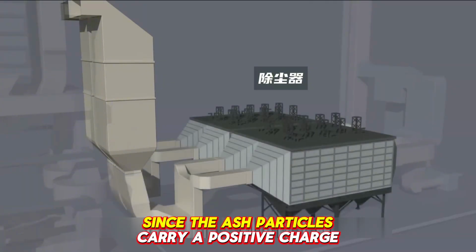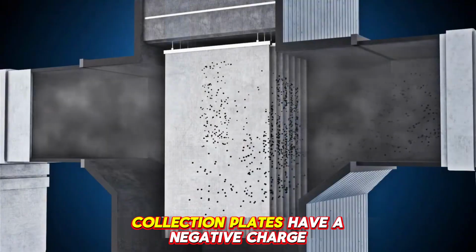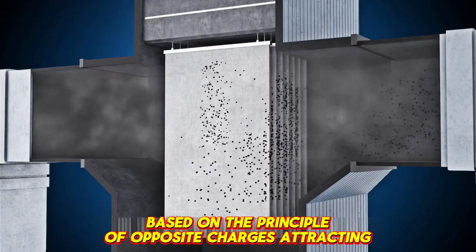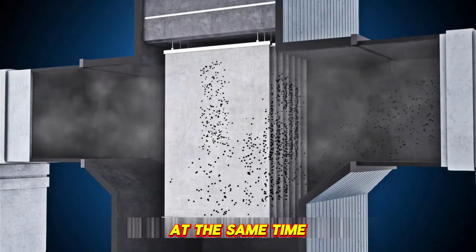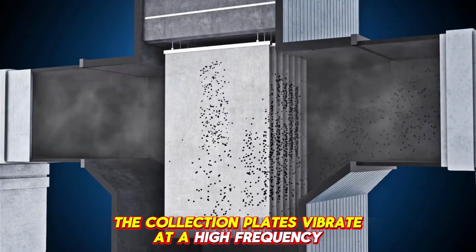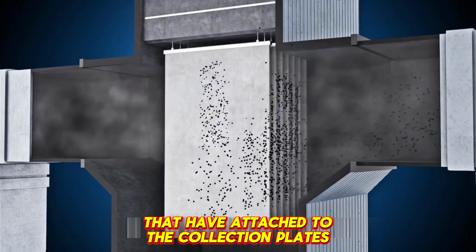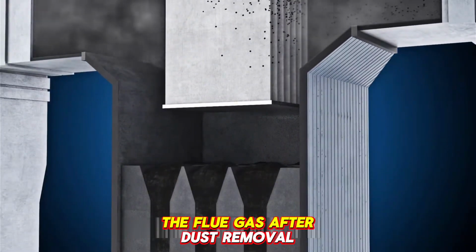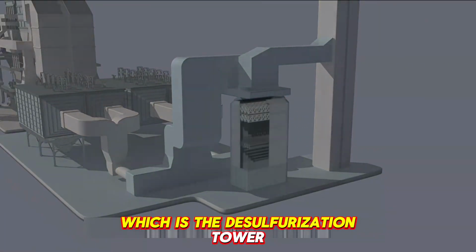Since the ash particles carry a positive charge and the electrostatic precipitator's collection plates have a negative charge, based on the principle of opposite charges attracting, the ash particles are attracted to the collection plates. At the same time, the collection plates vibrate at a high frequency. This shakes the ash particles that have attached to the collection plates off and into the ash hopper below. The flue gas, after dust removal, then arrives at the next unit, which is the desulfurization tower.